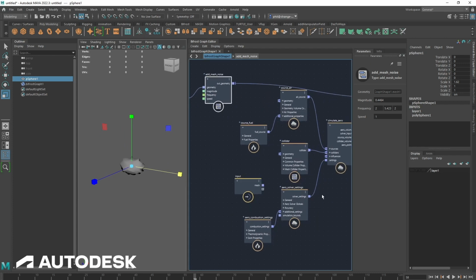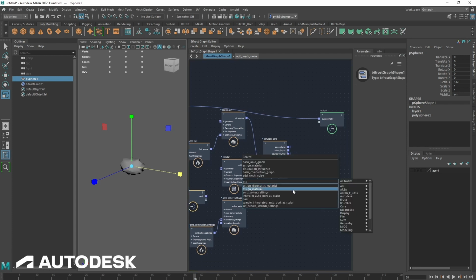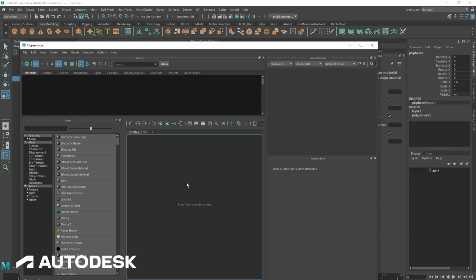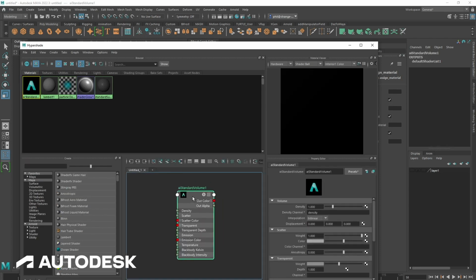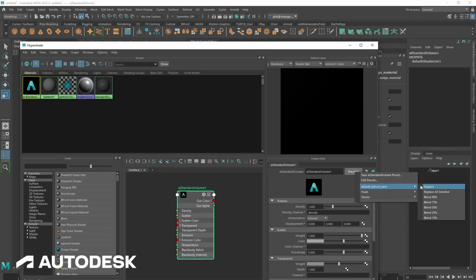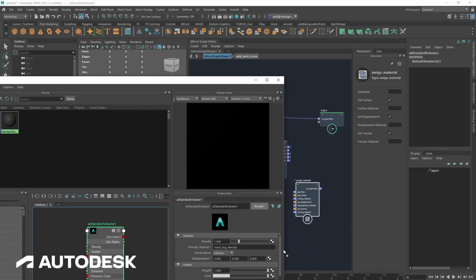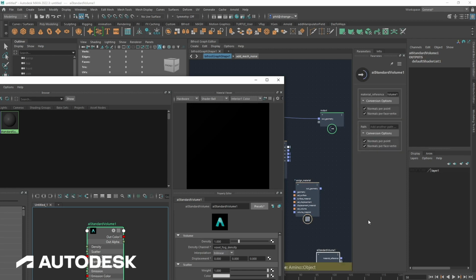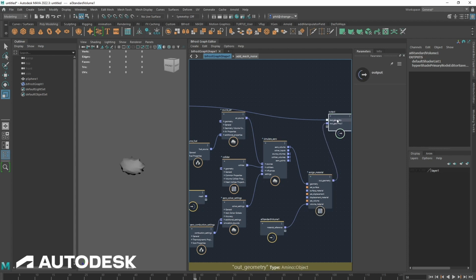combustion. So I'm going to leave that plugged in there, and I'm going to quickly create and assign a material. Just quickly go into the Hypershade, and in here I'm going to type in aiStandardVolume. That comes up, and in the preset I'm just going to go to default Bifrost aero, and leave that as that, and drag that into the graph, and we'll kill the Hypershade, and we're going to plug this into our volume material, and we're going to plug our volume into there and plug that into there, and there we go.